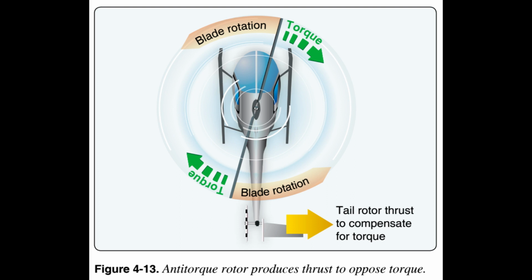Most helicopters drive the tail rotor shaft from the transmission to ensure tail rotor rotation, and hence control, in the event that the engine quits. Usually, negative anti-torque thrust is needed in autorotations to overcome transmission friction.